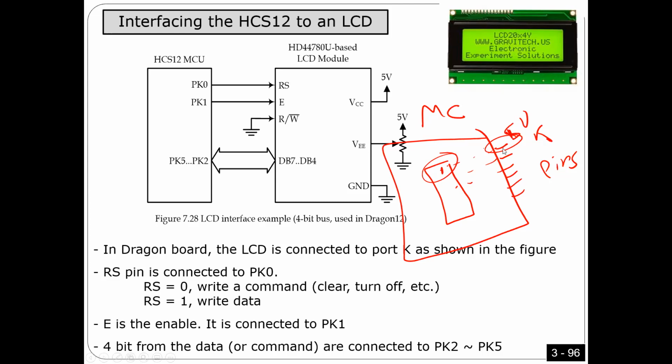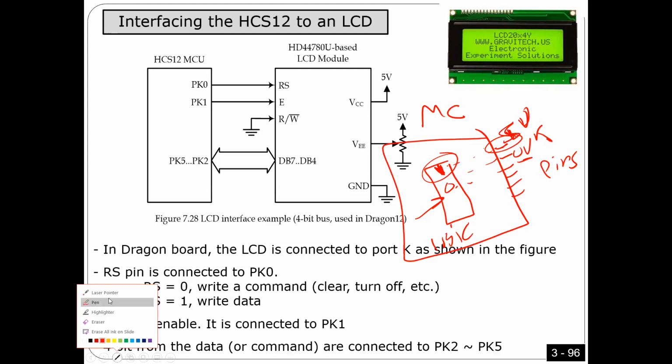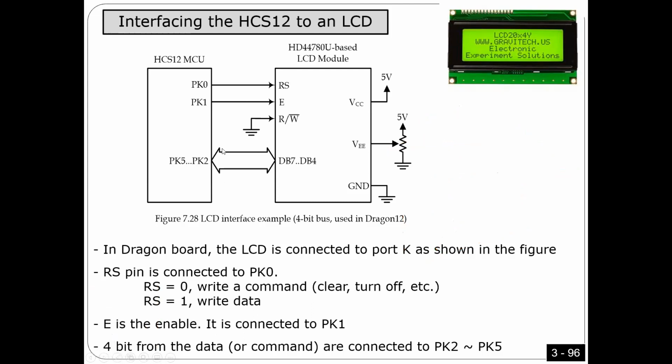When I say the pin, the only difference is that here I should say 1, because this is logic. Anything inside the microcontroller I should say in logic, so 1 or 0. But here I should say 5 volts and 0 volts. Anyway, don't be confused when I say bit or pin. It's the same thing. So now this is how the hardware is connected. Now look here, guys.